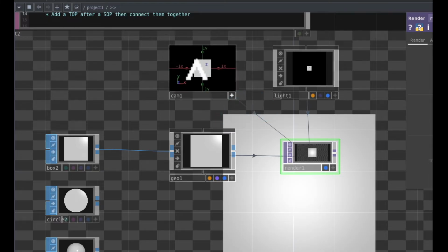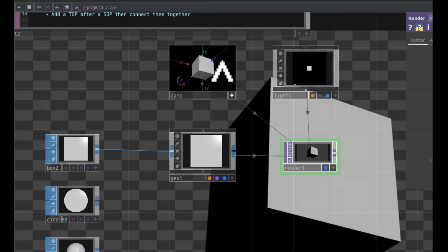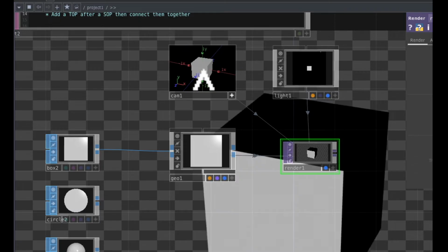You can see that the operator for the camera appears a little bit differently now. At this point, you can see the cursor changes after we click that viewer active button. And what you want to do is just click and hold and drag in the view until there's a different view. And now you can see that adjusted the camera. So that just changed the camera angle. You can click and drag one more time to change the camera angle again.